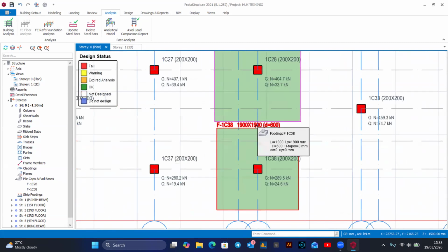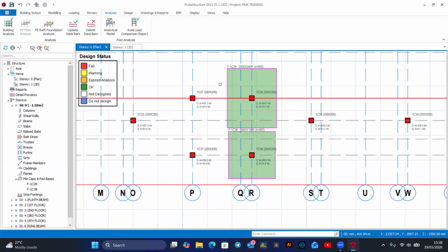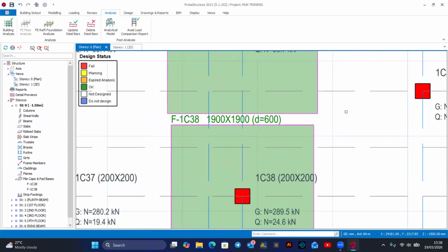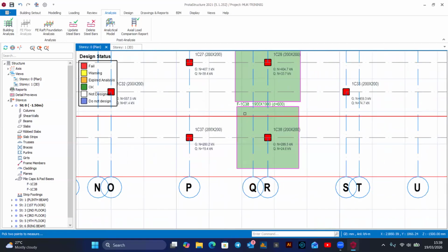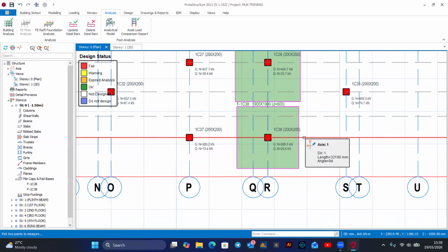Now, you see, when you look at these two footings, there is no possibility for them to be cast without having an excavation combining the two. Because now there is less space left here. If I try to measure, this is even 100 mm. Remember, this is the exact footing that will be cast, but there might be need for formwork on either side of the footing.